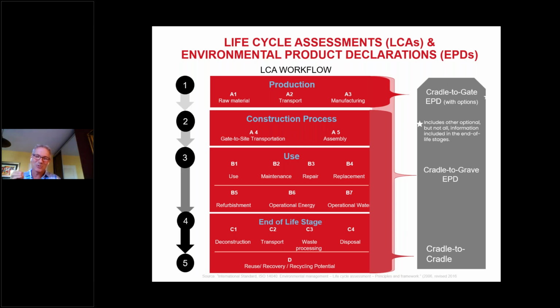So you, as astute specifiers of products, want to make sure that no one in their marketing is trying to hoodwink you and maybe say, oh, I have this great EPD. It's a cradle to gate EPD, environmental product declaration. It tells you all of the environmental sins and burdens on the environment for my product, but just A1, A2, A3. So that'd be kind of like, right? Not the best kind of full way to compare the full burden of one product to another. You at least want to be able to have the construction process in there, the full embodied energy.